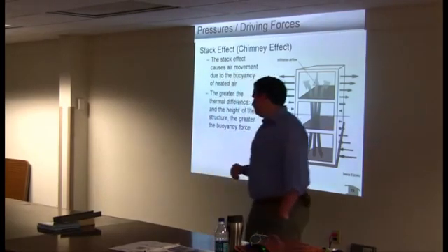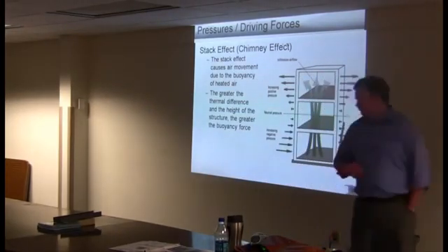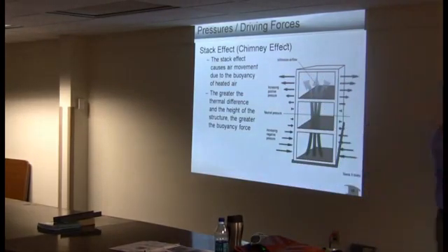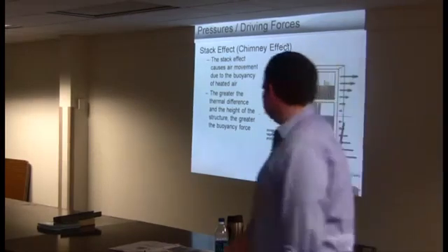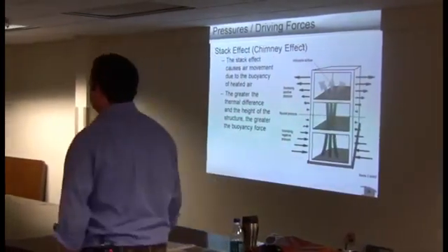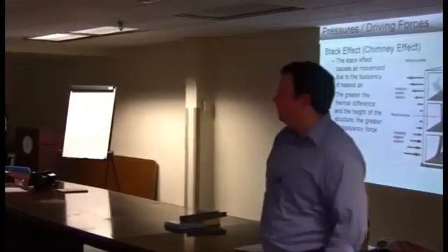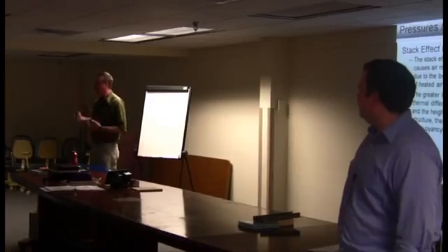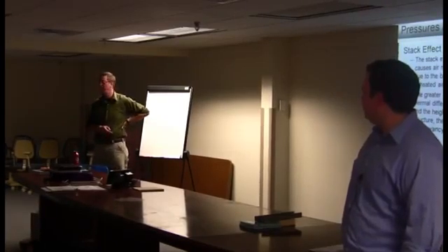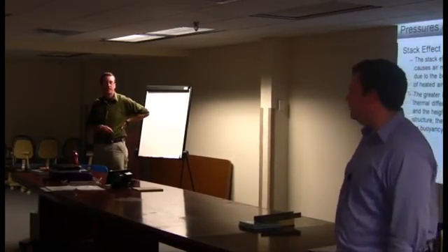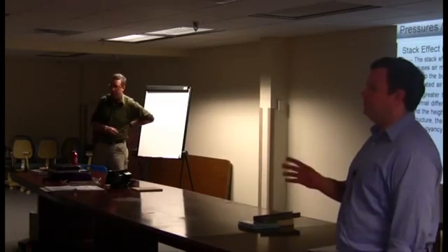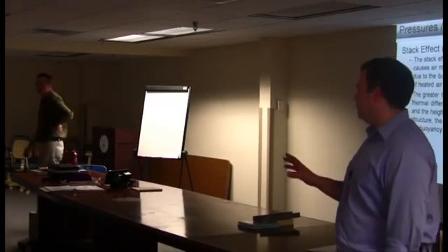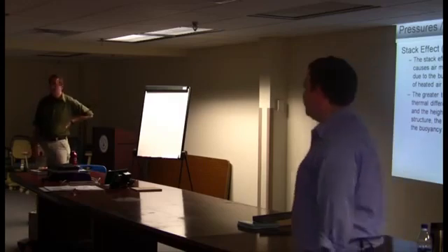And you're going to see this showing up in the Energy Code, because the Energy Code is starting to push harder and harder for kind of an airlock down here at the entryway, basically vestibules. Vestibules become bigger and bigger, it seems, as the Commercial Energy Code progresses. And as you go to taller buildings, it becomes more of an impact. We're going to look later today at how the two different code pathways have two different recipes for what you need to do with vestibules, and we're going to look at that this afternoon.